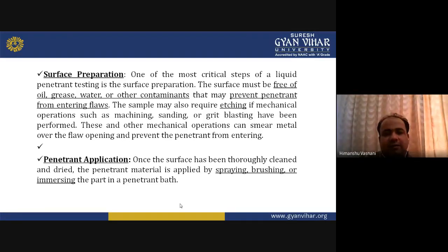Immersing is possible if you have a small part; otherwise it is applied by spraying or brushing. Spraying takes less time as compared to brushing, so nowadays the spraying technique is commonly used in penetrant application.